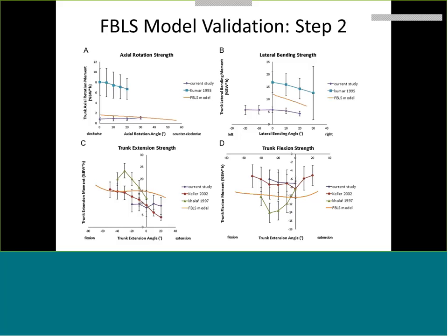Let's see, that's a good question. I think based on the tools that are available in OpenSim, I'm not sure if there's one where you can directly calculate stress. You can definitely get those internal joint loads using the joint reaction analysis. That's a good question, though. That's something I would need to look into a little bit further and see if maybe anyone else has done that yet in OpenSim. I'm not aware off the top of my head, though.